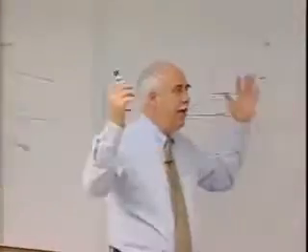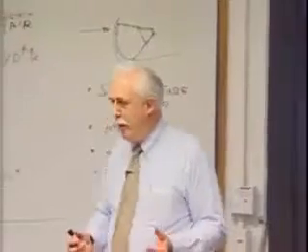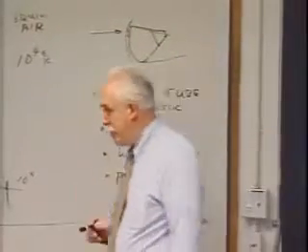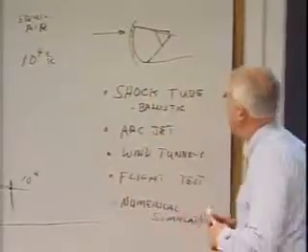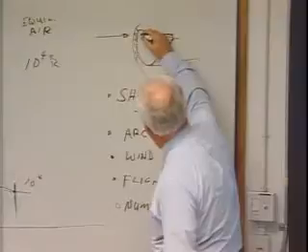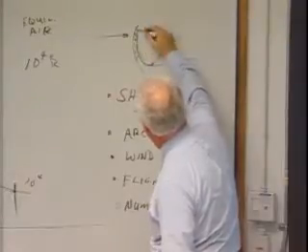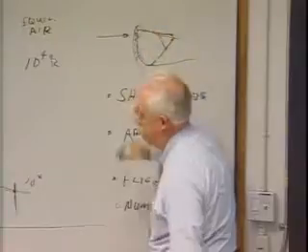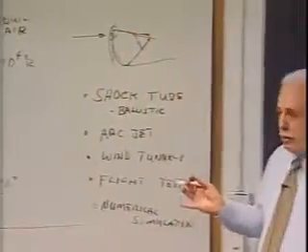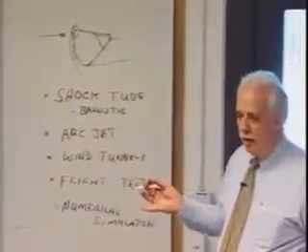Now, everybody tells us we were twice too heavy on the ablator on a capsule, and I'll explain that in a bit. It's a systems engineering problem. We got away from it on Shuttle, so pay attention when I get to that problem. In any event, we were a factor of 2 high over most of the vehicle, but not in this region. In that region, we were right on. Not by knowing what we were doing, just by luck.